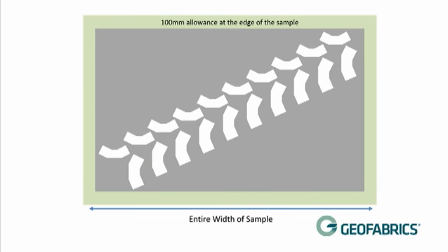The specimens are sampled so that they are as widely spaced as possible over the whole surface of the sample, so that their positions are symmetrically different in the longitudinal and cross directions. 100 mm from either edge. Any visually non-representative, soiled or damaged part of the sample is discarded.